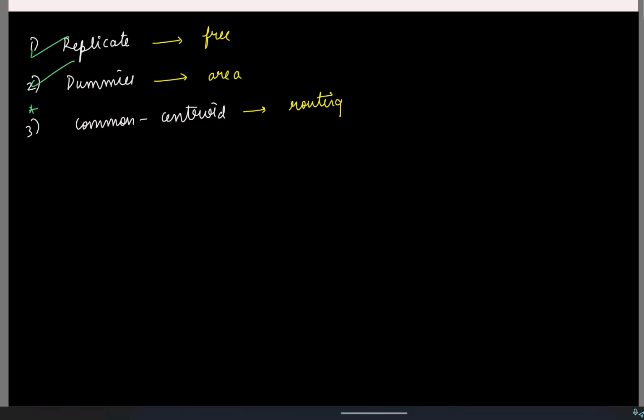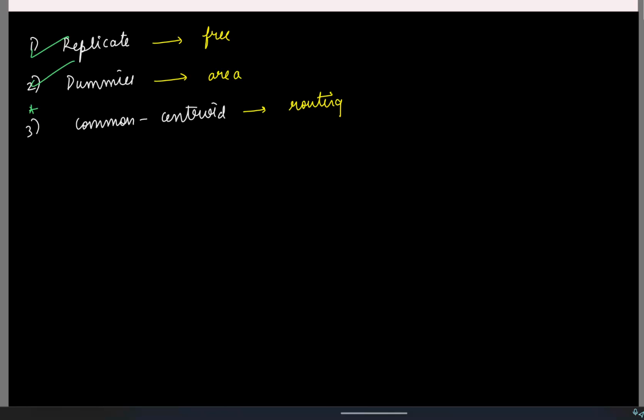So that is about the resistors. Now let's come to our op amp. Even with respect to the MOS transistors, the same guidelines which I mentioned here hold good. Let's say we look at our tail transistor, and let's say it's biased using a current mirror like this. This goes outside, where I provide the current. Let's say the ratio is 1:2 for simplicity.